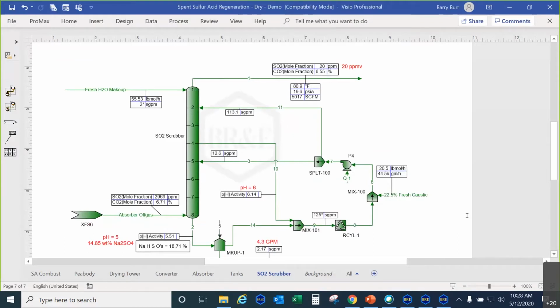I think it would work fine to use a single burner, and I think you would get the same answer if you used a single burner and the final outlet temperature of the second burner as your target. It's just because this particular plant had two burners and two different temperatures to target, but in general, I would probably use one burner and one outlet temperature.